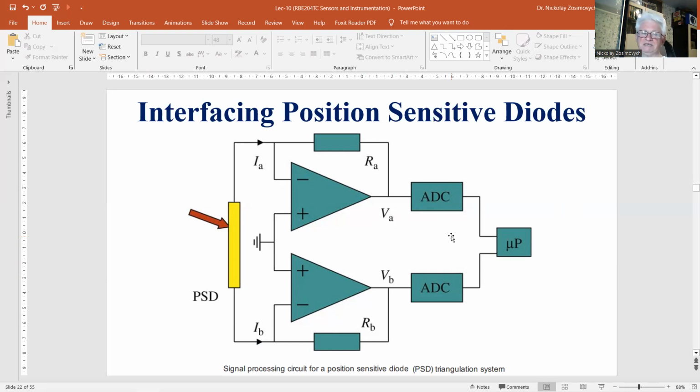The best performance is obtained when the output range of the IV converter matches the input range of the ADC. In that case, the system takes the most advantage of the full resolution of the ADC. However, the irradiance varies strongly with distance. At large distances, the output signal may drop below the acceptable noise level.